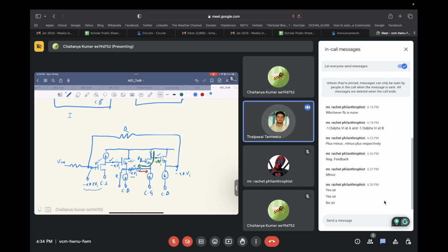Sir, after designing a circuit, I would like to know whether it is invariant to PVT, process, voltage, temperature. How can I check, sir? You can use the DC analysis. In DC you can get the operating points of the transistors in question, the transistors whose GM you have to fix. You can get the DC operating point of those things.